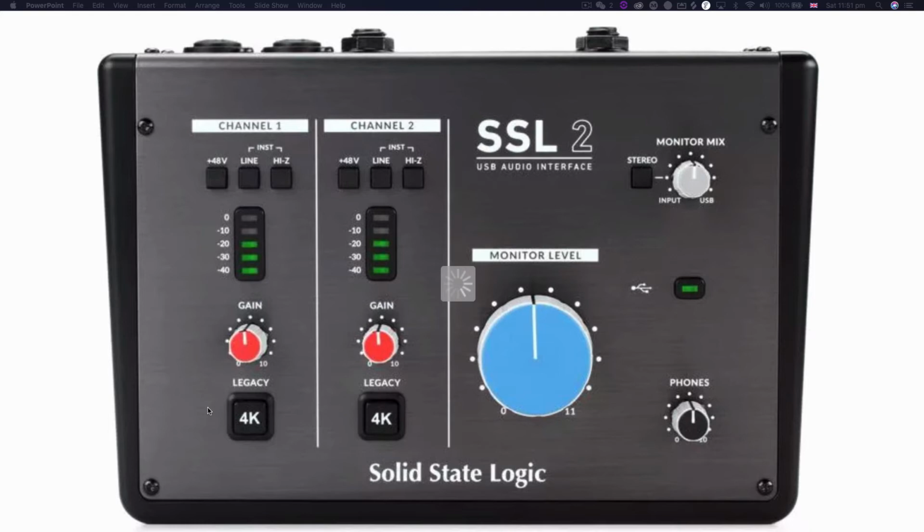As a general rule, green usually means safe, yellow means almost at the limit, which is kind of dangerous, and red usually means you've reached the limit, and the result is usually clipping, which is the thing you want to prevent all the time. Keeping your signal between green and yellow is good. But also keep in mind, don't be too conservative, otherwise you get a pretty soft signal. In my opinion, levels around -10 to -4 dB are pretty good. But never reach zero.